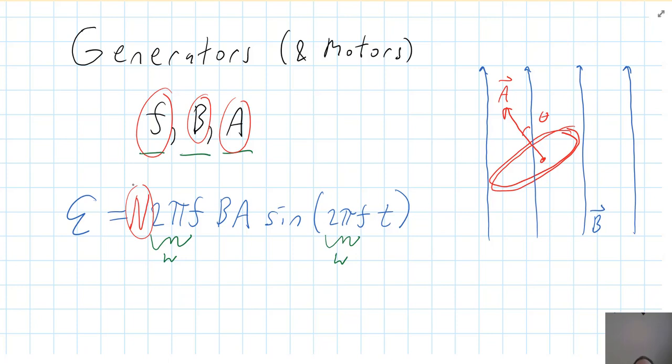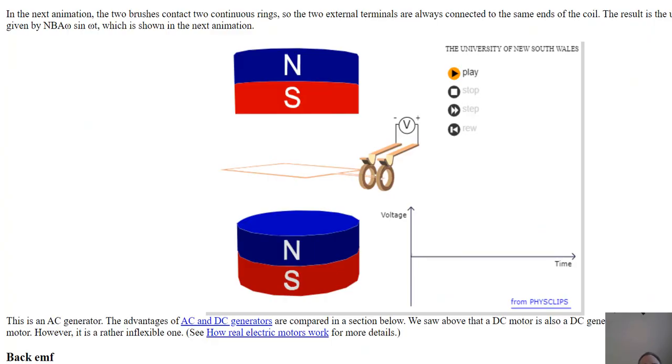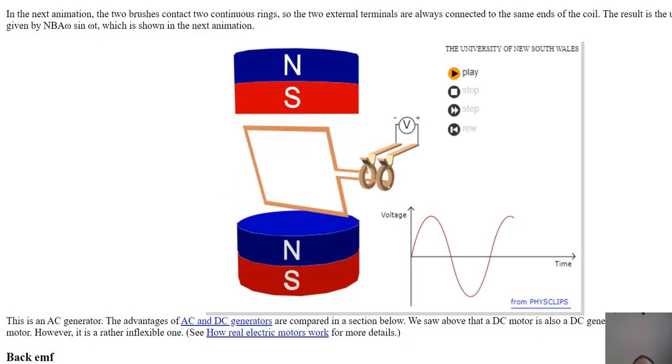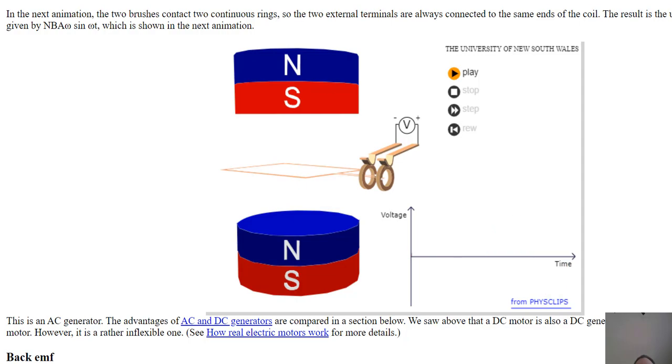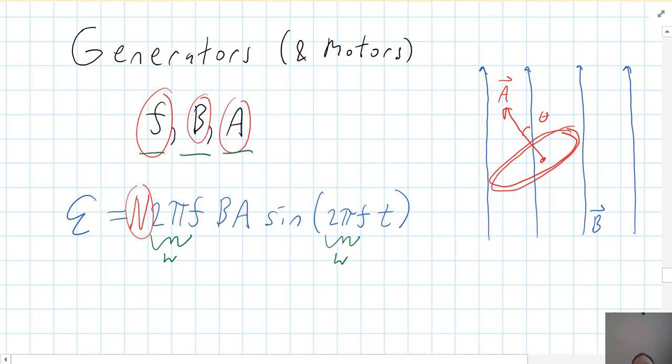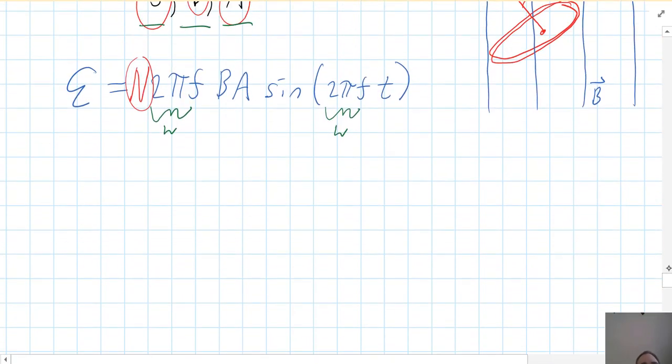Our electronic devices rely on a specific voltage. For us in the United States, it's roughly 120 volts at 60 hertz. If ComEd were to change voltage, that would be very bad for a lot of our electronic devices. So what does change over the course of time? Well, for any generator that works like this, something has to rotate that coil or coils, and that is something mechanical. Something is rotating that coil, and that rotational energy is then turning into electric energy. Now, we're going to look at the rate at which that's being done, and that's power.